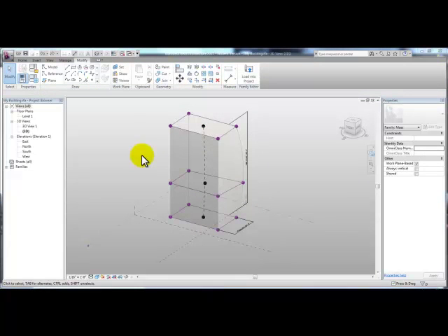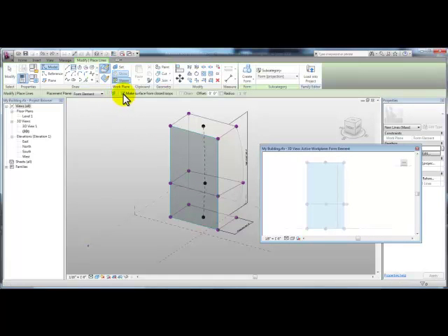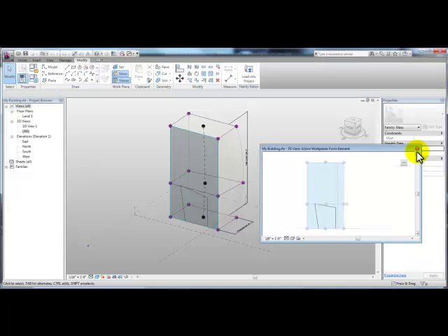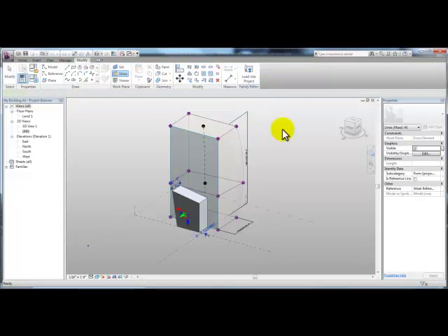Also, you can draw on one of the surfaces by picking Set and selecting that surface, and then picking Show to show that that's the surface that you're going to draw on, and then pick the viewer. And now we can draw right on that surface using the viewer. We want to take the check mark out of Make Surface from Closed Loops if you want to modify the closed loop once you've drawn it. So I'll draw a rectangle and then I'll select it and modify it slightly. Then in the drawing, I can select that rectangle and pick Create Form, Solid Form.